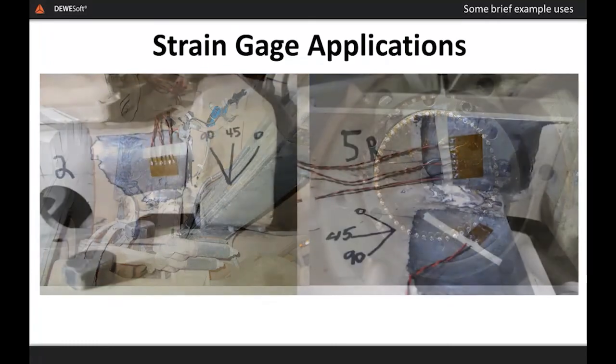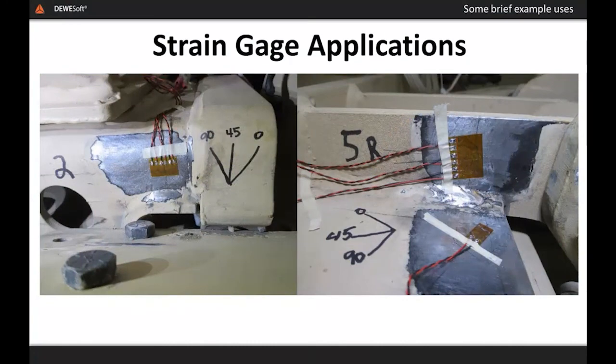In these images, you can see the surface preparation and the care taken to align the gauges in a specific orientation. The directional outcome is rather meaningless without precise knowledge of the individual element's alignment in the first place. Some software actually has pictorial references to these, as you saw earlier, so that you can relate them back to the angle pictorially as well as by the reference that you've applied to them. Another point of interest here is the placement, following the rules regarding the placement of the gauges to welds.